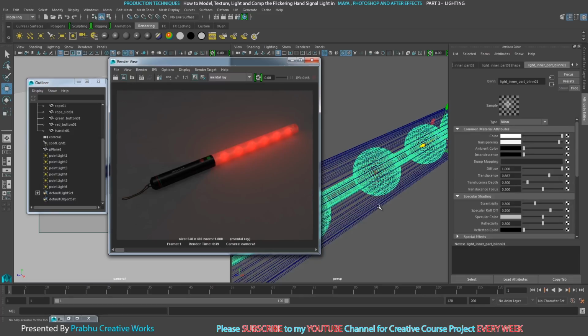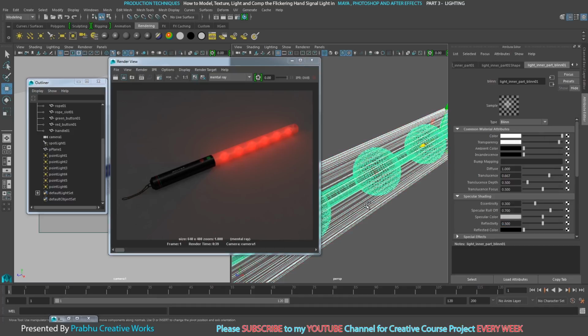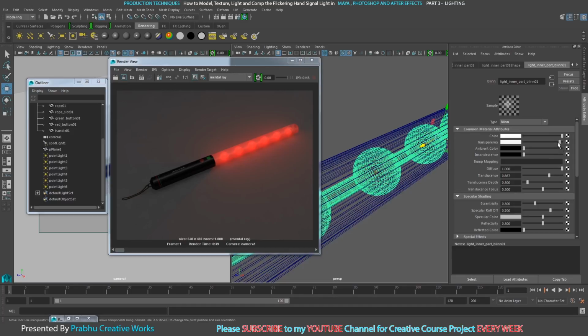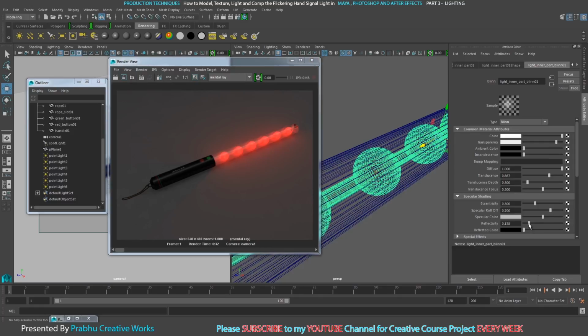So I will select this part, the outer part. Here I will enable my translucence amount, and I will reduce the translucence over here. So I will increase my transparency to full, reflectivity to 0.5 and specular color to high. Now I want to reduce the transparency amount for this object, so I will click render again. Now I want to reduce the reflectivity and specular color of this object.